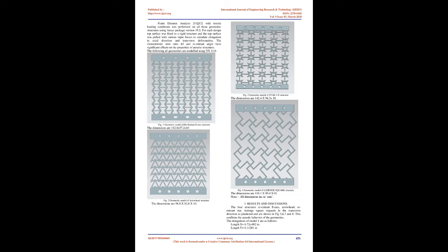Auxetic structures are efficient cellular materials that can absorb blast or impact energy through plastic deformation, thus protecting the structure. They are developing sacrificial solutions with lightweight, high specific strength, high specific toughness and excellent energy dissipating properties, due to their negative Poisson's ratio nature. The use of auxetic and non-auxetic panels in blast-resistant structures had been employed by developers. Nonetheless, implementation of those energy dissipators, explicitly as a uniaxial passive damper, is restricted to limited studies, which highlights the potential need for further explorations.